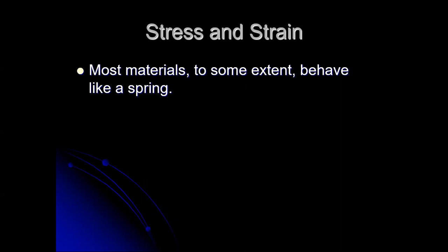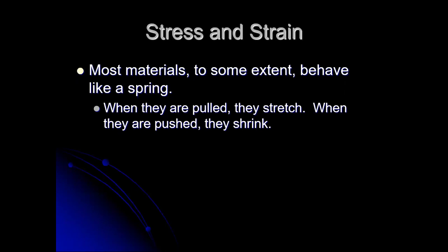Strain is a reaction to stress, but it's the material's reaction to stress. We can add that up and get the overall deformation. That's one of the things we'll do: figure out if we've got a 20-foot long piece of material and we apply force to it, how much bigger does it get? But to find that, we first need to find the internal values, the strain, how much each inch grows or shrinks if we're dealing in compression.